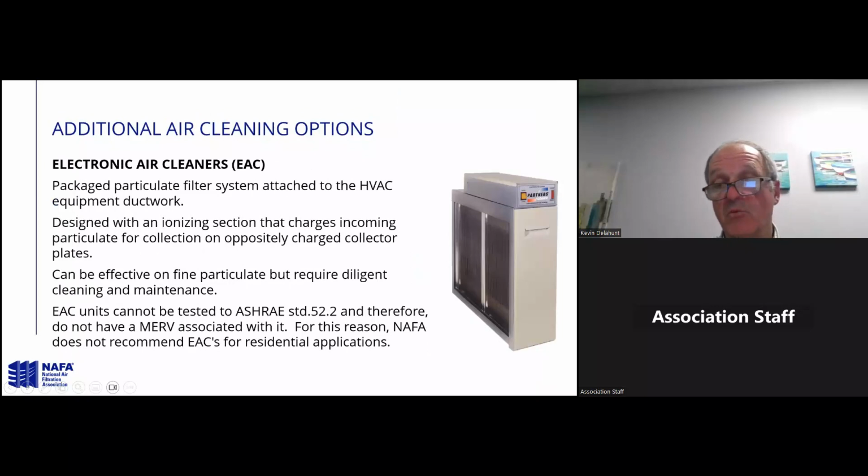Electronic air cleaners, at one time they were extremely popular, very high efficiency, and can replace the mechanical filter. The downside is the possible creation of ozone, and the maintenance on them is quite laborious. So in a lot of cases they don't get serviced as often as they should, and the efficiency of the product diminishes as the plates start to get dirty and they don't transfer the electricity as evenly.